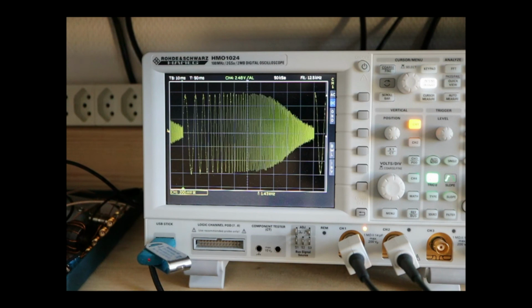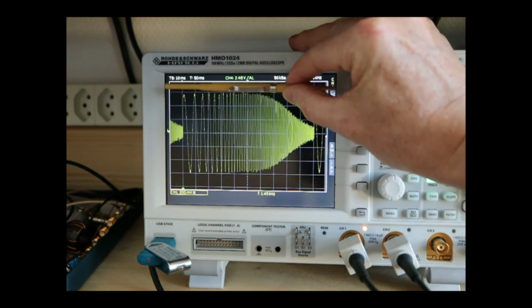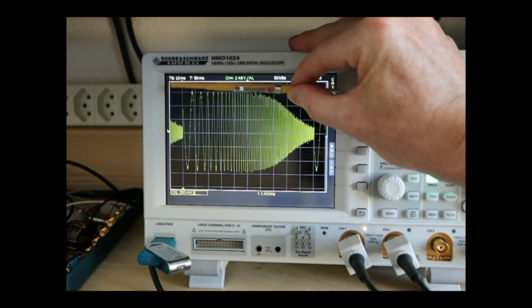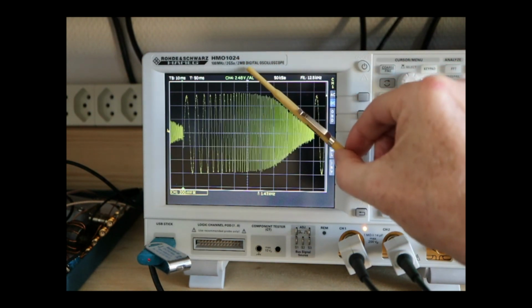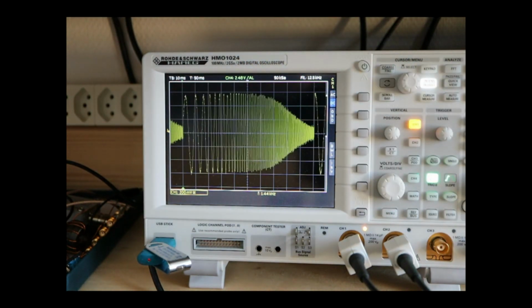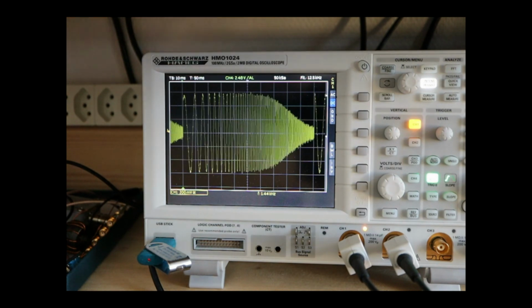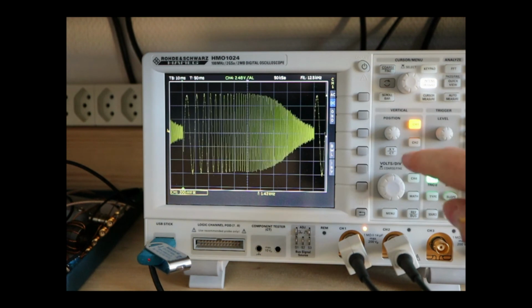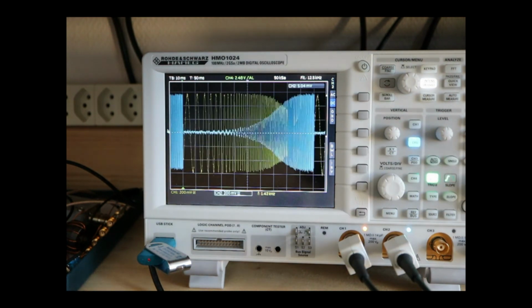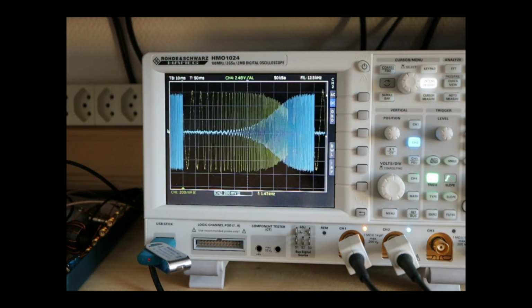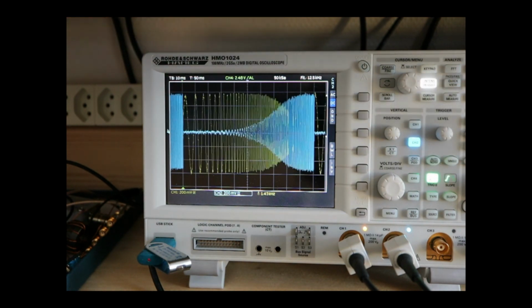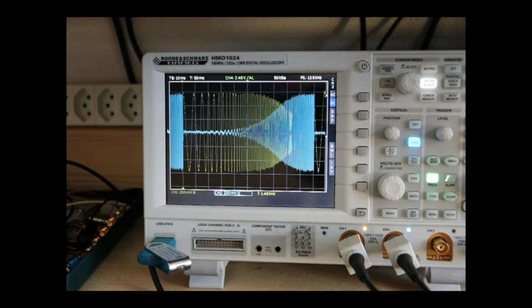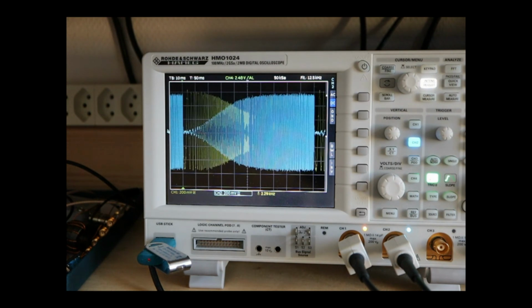a Bode plot where you have constant attenuation or gain, and then you have your 40 dB per decade roll off of the low pass filter. And then we can also take a look at the high pass filter. On a Bode plot it looks like this. You see the blue is now the high pass overlaid, and I can switch back again to linear sweep, and